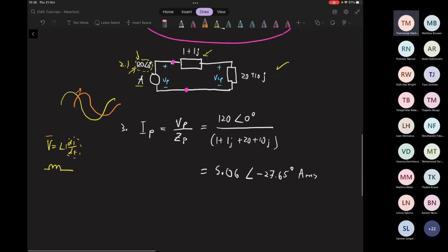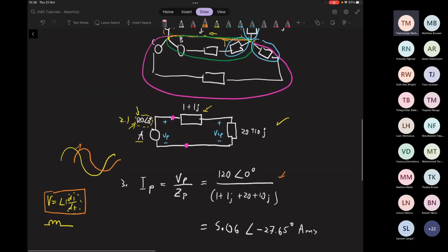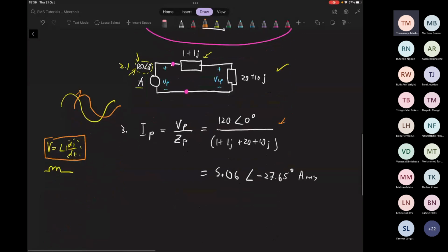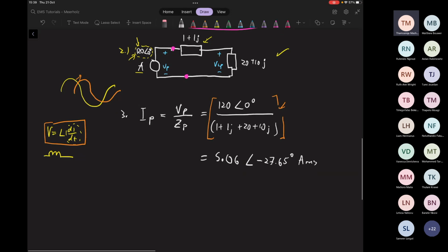Yeah, so phasors beautifully do this all for us by just doing this complex division on a bunch of constraints that everything's moving in kind of the same way. We can just do a simple division like this with complex numbers, and it will represent actually taking derivatives, because you still get cosines and sines out. As we can see, our answer is still a sinusoid because it's a phasor, which is quite interesting. All of our answers are actually going to be sinusoids. We put a sinusoid in, we get a sinusoid out. Quite beautiful. I don't know if you guys are following that, but that is quite a cool thing.